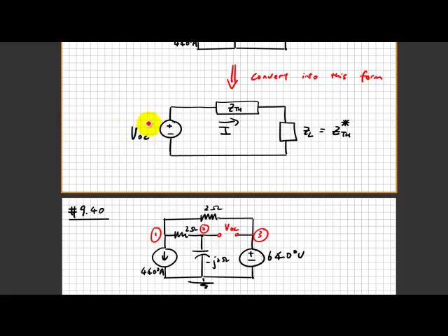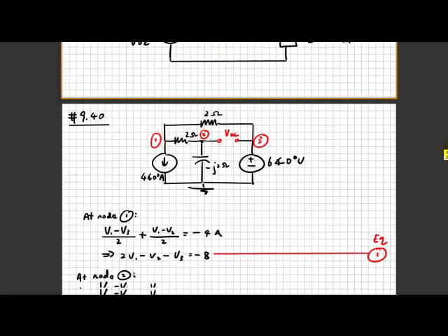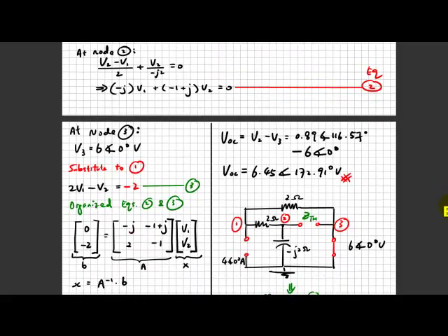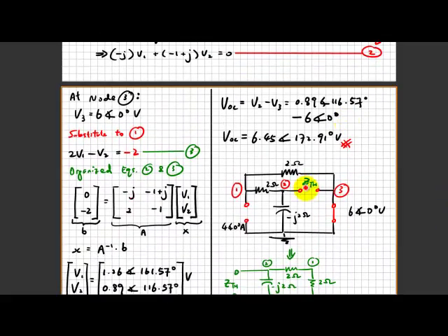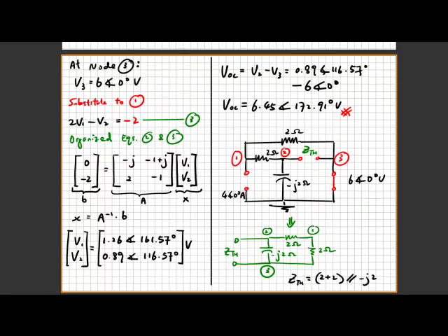So the next step will be to find the Thevenin equivalent impedance. Let's go again. What I did was copy the whole figure and put it right here and label it in green to show the emphasis of what we are going to find. So you're looking at the Thevenin equivalent impedance Z_Th: open the current source and short the voltage source. I repeat, open the current source and then short the voltage source. So in this case, you have an open circuit and you have a short circuit.